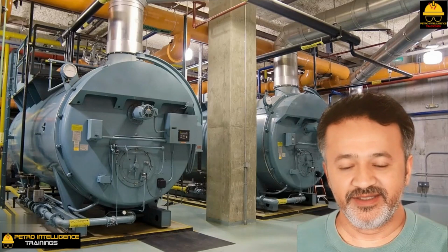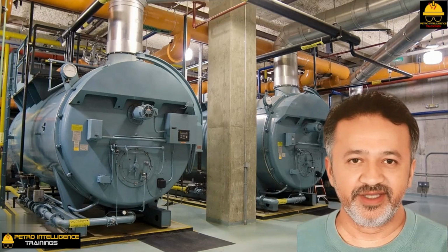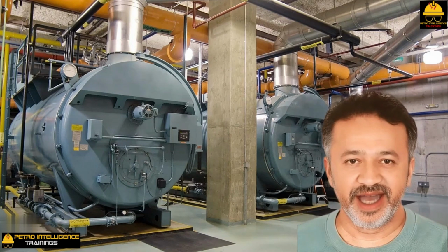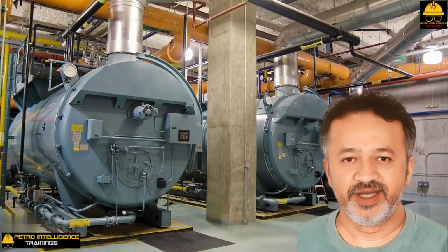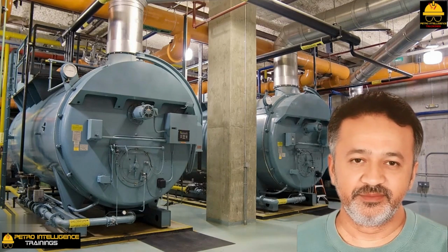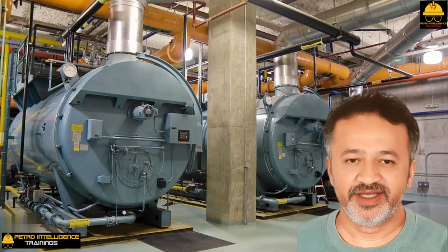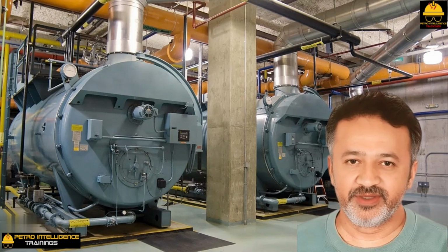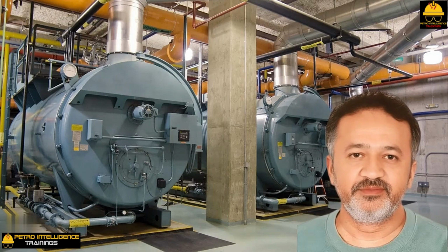Boiler blowdown rate. Although boiler feedwater, BFW, has been treated to remove minerals, residual contaminants, carbonates, and silicates are still present. These minerals, especially the silicates, are bad, as to some extent they are going to be entrained into the generated steam. The biggest problems with entrained silicates, TDS or total dissolved solids, are drying out on the steam superheat coils, which then fail due to localized overheating, which results in superheat tube failure.